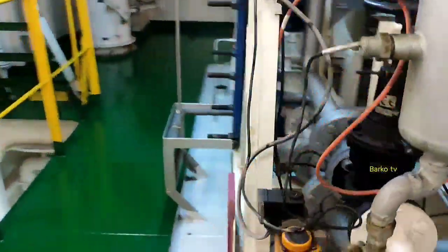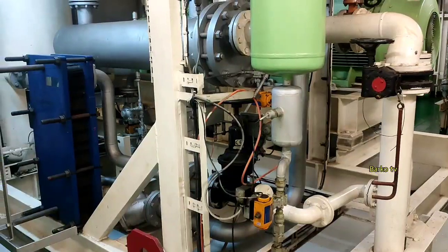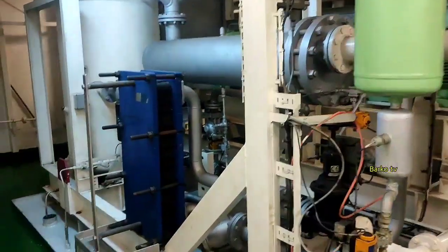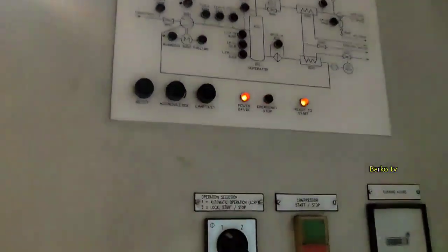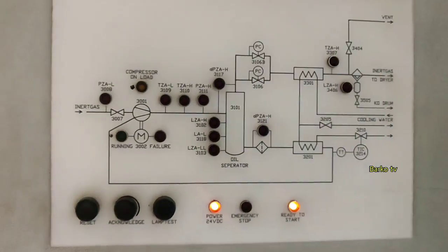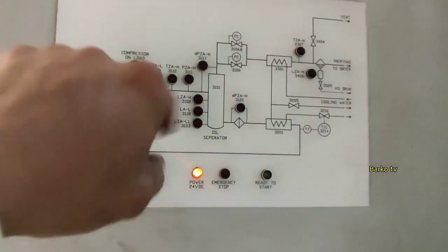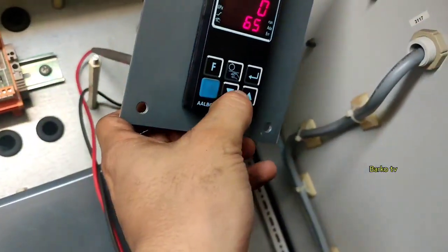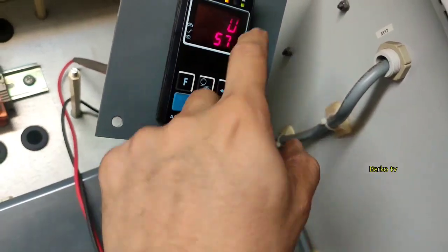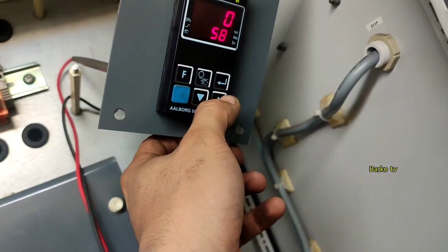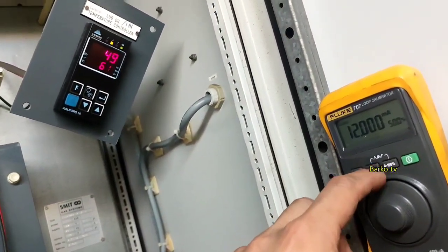Example, that set point on the lube oil controller is 65. It means this seawater valve opens and closes for the position until it satisfies the 65 temperature. As you can see, there is no indicator for lube oil. Okay, that below 65 is the main issue. We need to set that one to 65 or 66 or maybe 70.